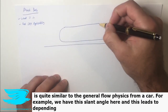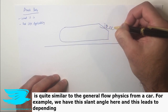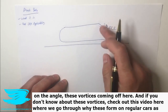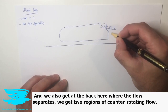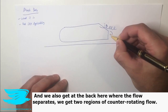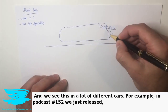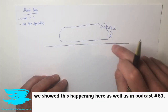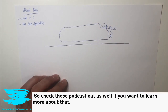For example, we have this slant angle here, and this leads to, depending on the angle, these vortices coming off here. And if you don't know about these vortices, check out this video here where we go through why these vortices form on regular cars as well. And we also get at the back here, when the flow separates, we often get two regions of counter-rotating flow. And we see this over a lot of different cars. For example, in podcast 152, which we just released, we showed this happening here as well as in podcast 183. So check those podcasts out as well if you want to know more about that.